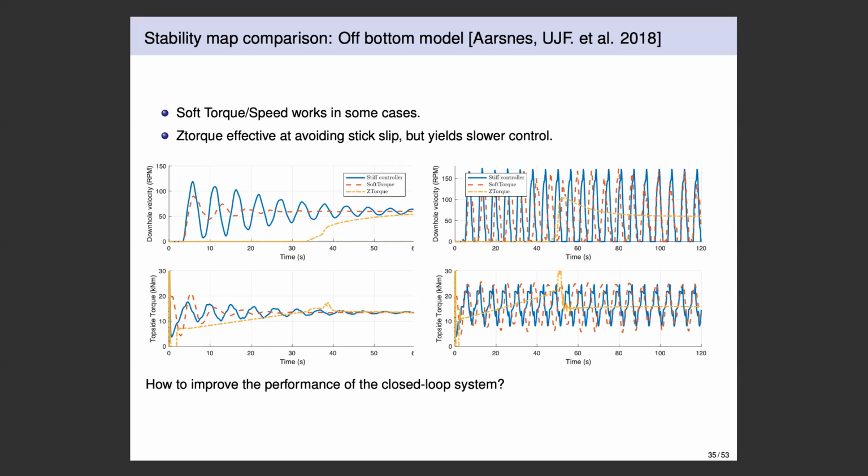And maybe some research that you can go on, Jean and Florent, is what is the impact of time for your connection on your static friction evaluation when you have differential sticking, which is happening there, because your static friction will climb up to very, very large values the longer you have a delay for restarting the top drive during your connection.